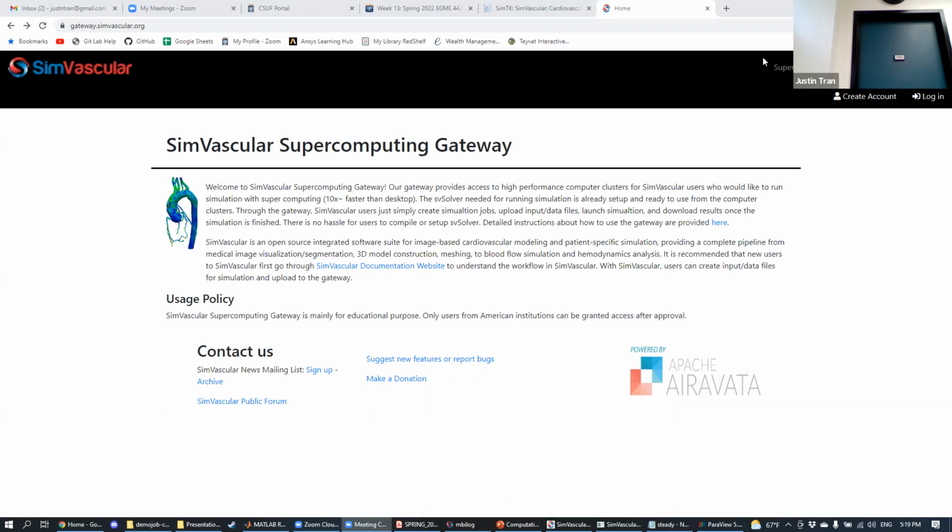Another thing you can do to debug it is that usually the problem is in just one region of the model. Normally when you create the model you select every segmentation, so try doing one at a time: mesh this one, then a second one. Usually that will help you narrow down the errors, because usually it's just one or two vessels that are giving you trouble, and you might have to go back and modify the segmentation. There's a lot of things, so that's why Tuesday we're going to have another work session. Just give your laptop a break for today.